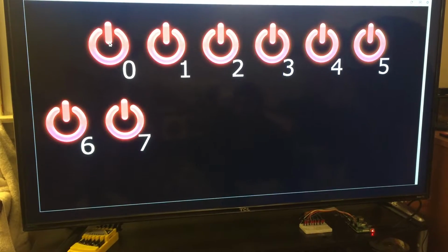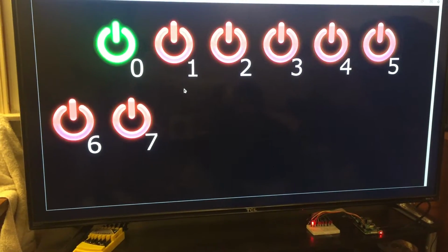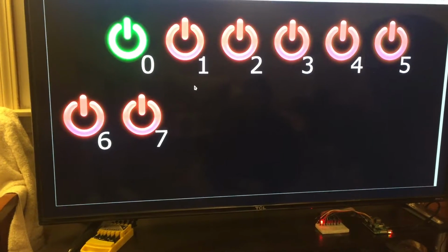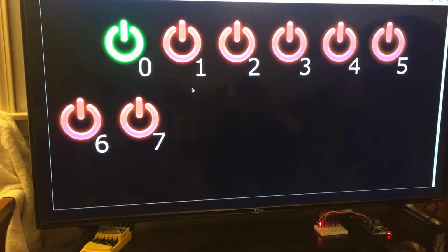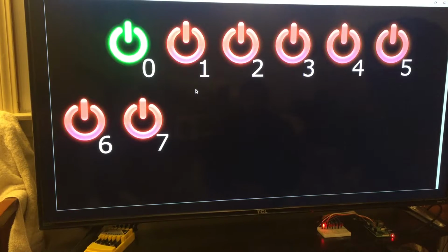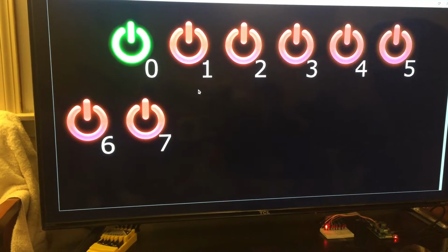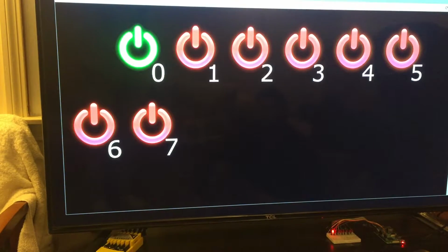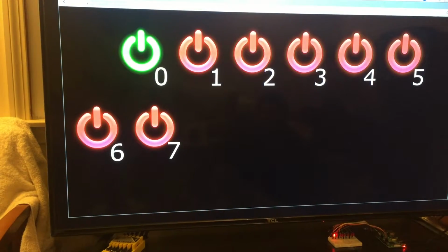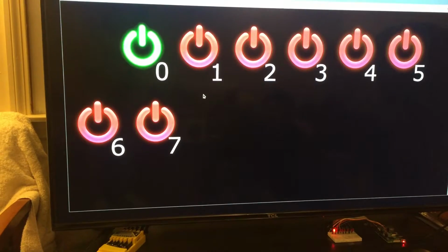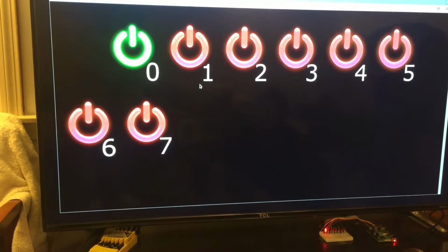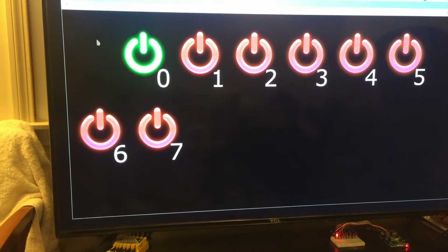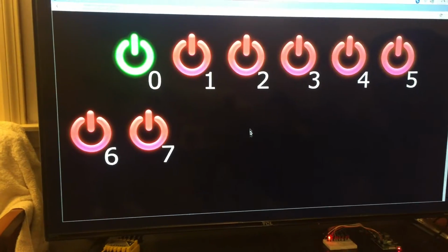So when I click on this button, the image turns to green and we see the LED is turned on. Right now we're using our laptop, and we just set up the browser and put the IP address of Raspberry Pi, because the web server that has been created uses the IP address of Raspberry Pi, and we can see this image.